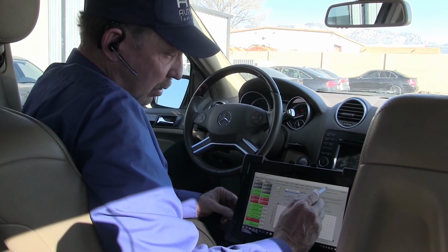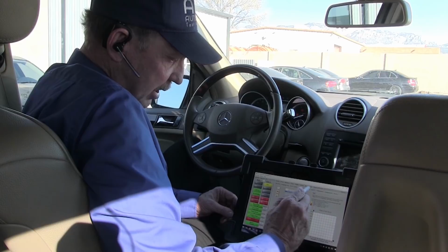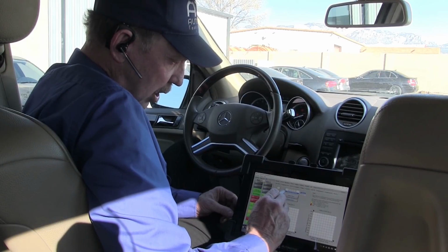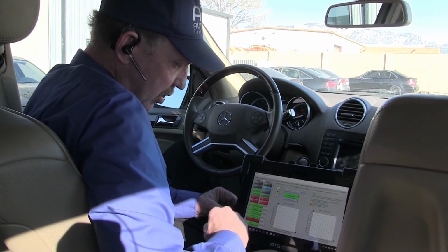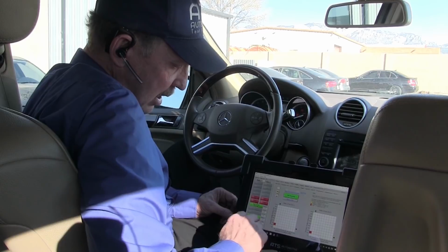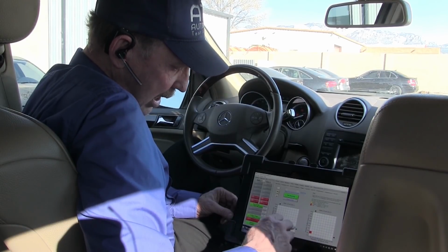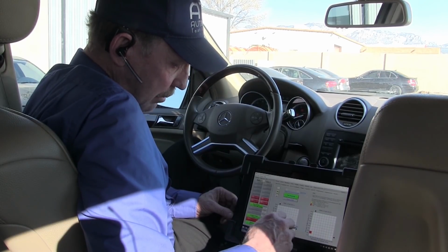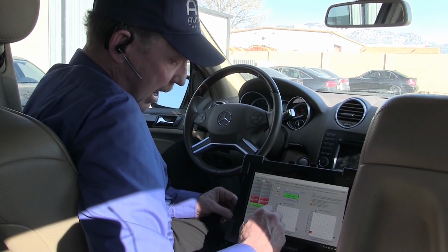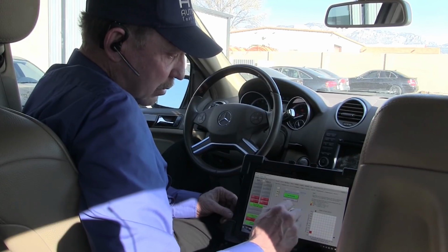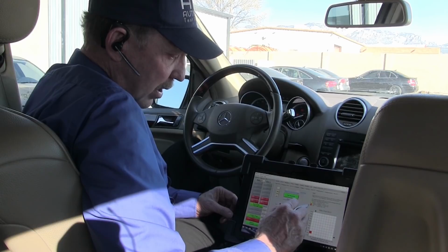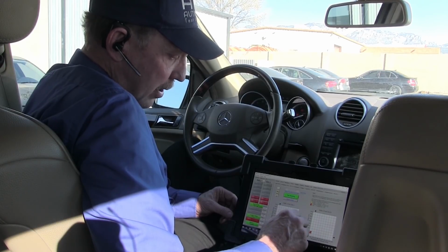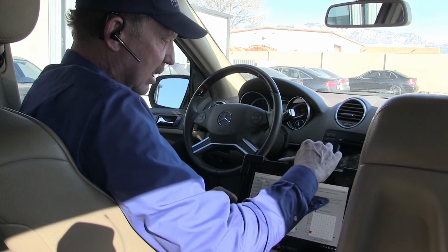So the first place I want to go is the sharpshooter in the eSCAN, and I want to pick total trim, long plus short, and we'll start it and load these graphs. We can see that if it's red, it's bad, and if it's green, it's going to be good, and if it's orange, it's pretty bad, and yellow. The way this works is green and yellow are okay, and orange and red are broken. So this is broken, as we can see.